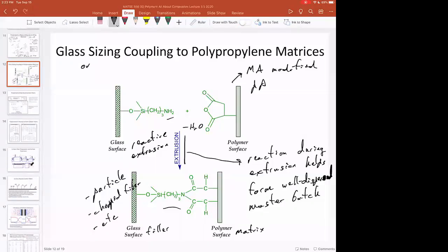Glass or clay, because the chemistry is similar for clay because it's an aluminosilicate. And so you can still use silane coupling agents and some other surfactants for clay composites. And of course, clay is really cheap. And so one of the first composites that was used widely in automotive was a clay polypropylene bumper for Toyotas. And so that's still quoted as one of the big first examples. And so Toyota came out with this plastic bumper, and it was a clay polypropylene composite that they designed.